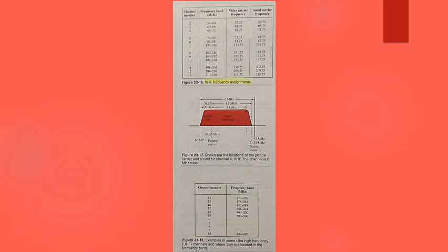In commercial TV broadcasting, the upper sideband is transmitted without attenuation. The lower sideband is partly removed by a vestigial sideband filter at the transmitter. The curve in figure 23-17 shows the basic response traits of the TV transmitter. The sound is transmitted as a frequency modulated signal at a center frequency 4.5 MHz above the video carrier. In channel 4, the sound is at 71.75 MHz.